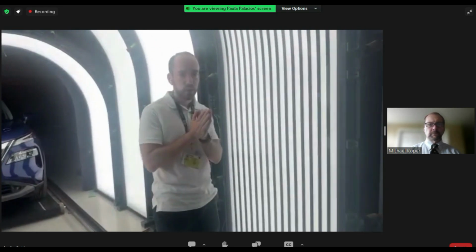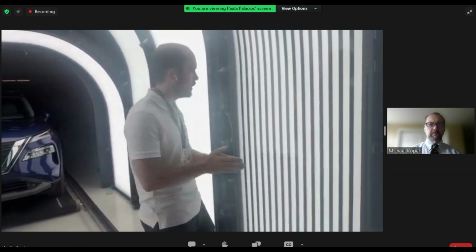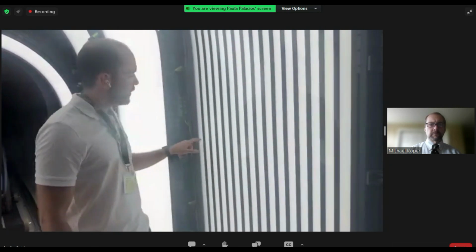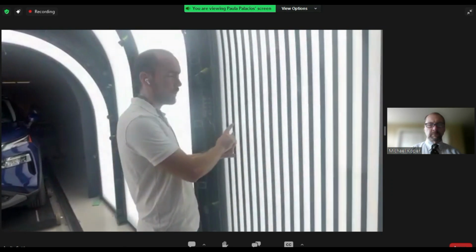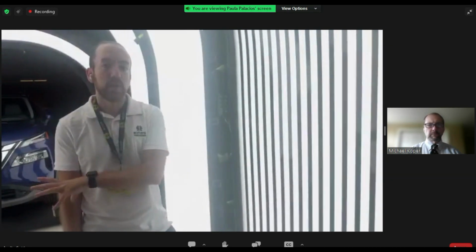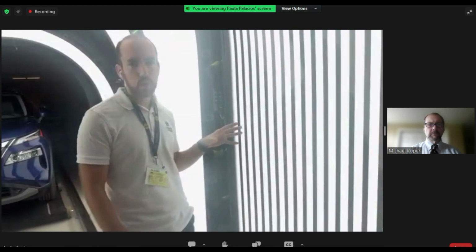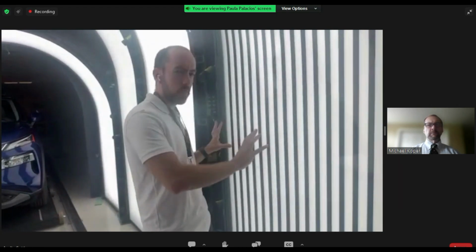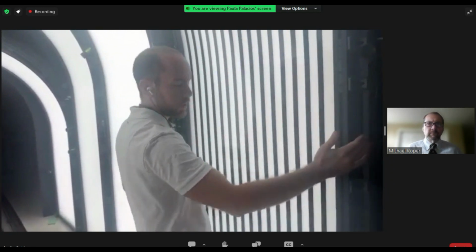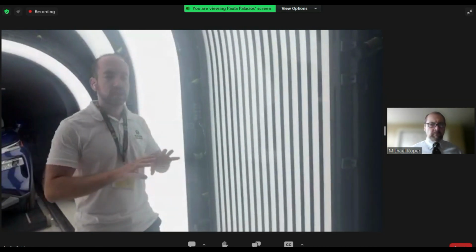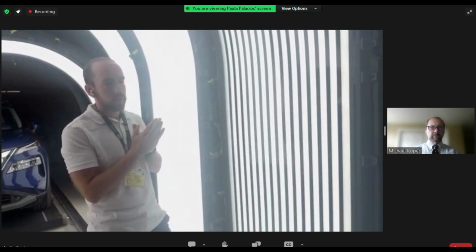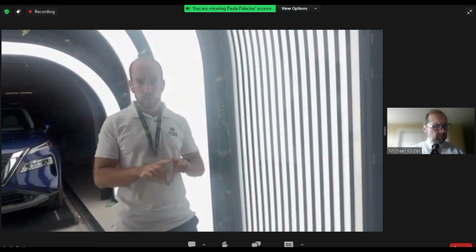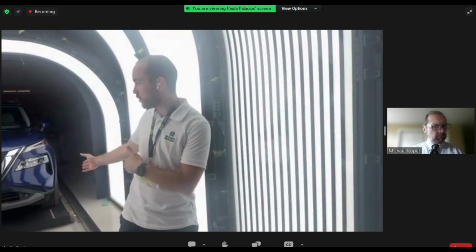The first one is the Surface Damage Inspector, or SD. This SD is working with several cameras and a zebra light. This zebra light, this black and white reflection in the car, is helping us to detect not only scratches, but also dents. We are composing, with thousands of images in every cycle, a super image with the information that is required to have all the detections. Later on, we will show you an image of how this car is going to be inspected.